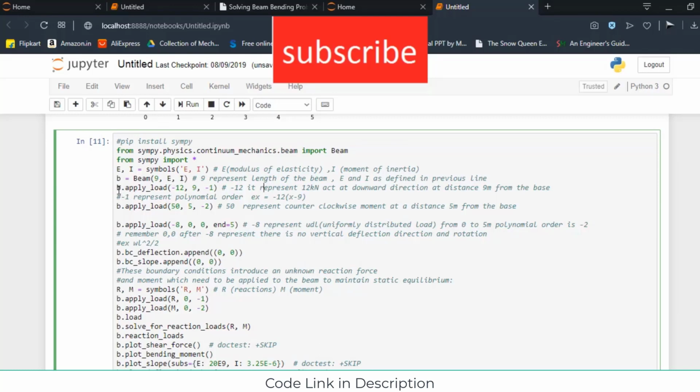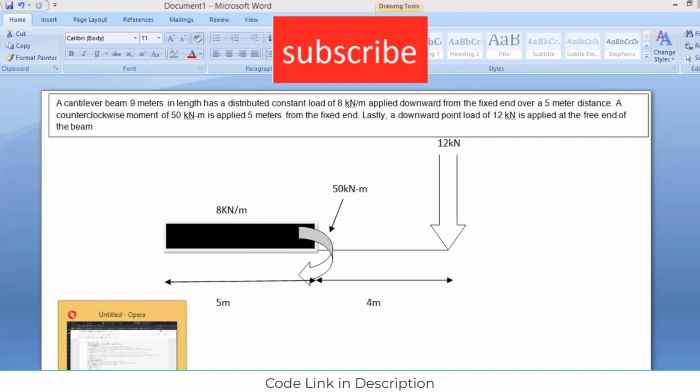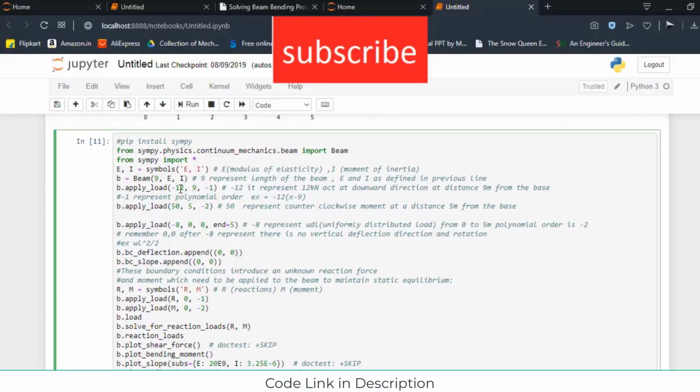So first of all, what I have done is b.apply_load(-12, 9, -1). So minus 12 is basically the point load. As I told you earlier, the point load acts in the downward direction. If, for example, the code had 12 kN instead of minus 12, then the load would act in the upward direction.